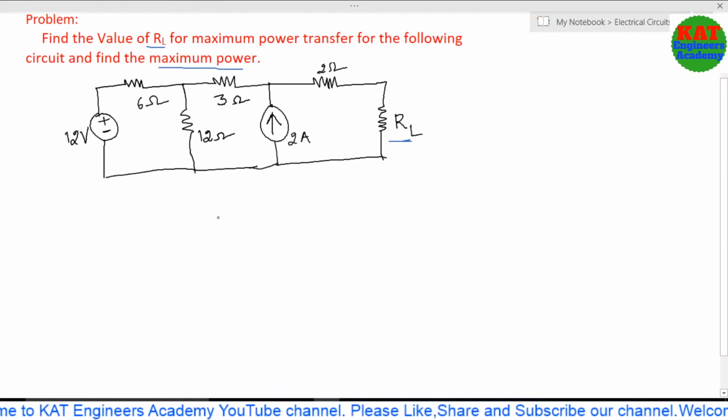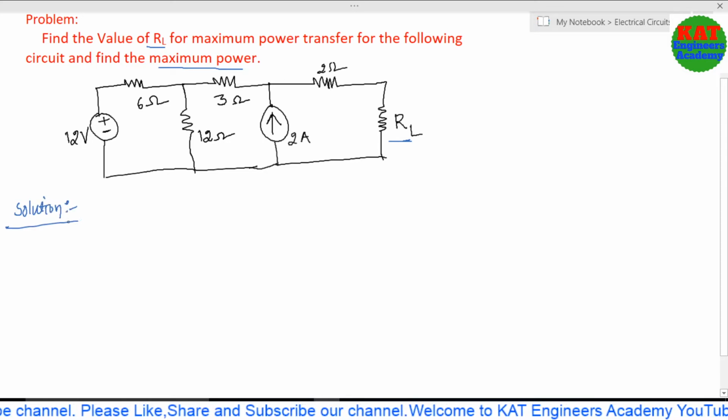The maximum power transfer theorem says that the maximum power is delivered when RL equals RTH. So finally we need to determine RTH, and that RTH is nothing but the load resistor. Okay friends, so it is indirectly just like Thevenin's theorem only. How we analyze the problem using Thevenin's theorem, like that only we have to solve the problem. It is a repetition of a Thevenin's theorem problem only.